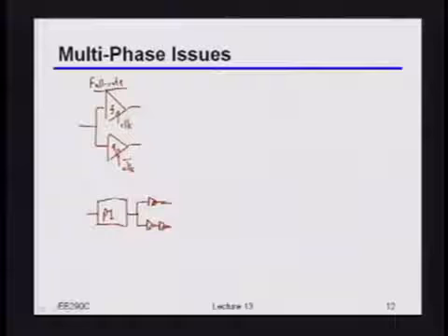But let's say we actually wanted to use multiple clock phases. We wanted to do time interleaving because we want to run really, really fast, much faster than we could get an oscillator, or at least a ring oscillator, to run. Let's take the simple example where you do what's called double data rate, often referred to as DDR.